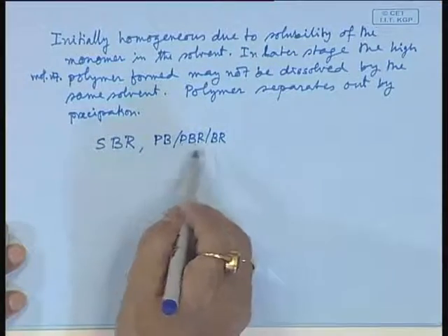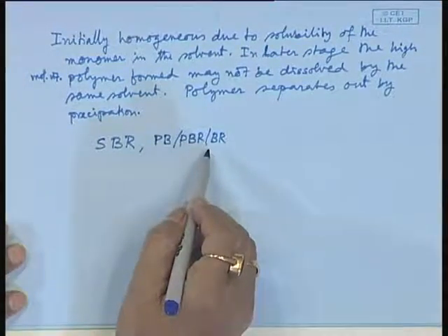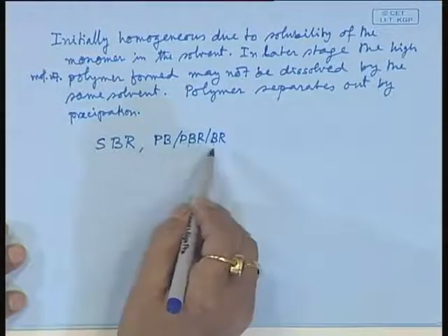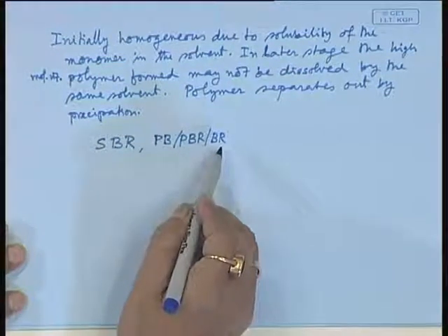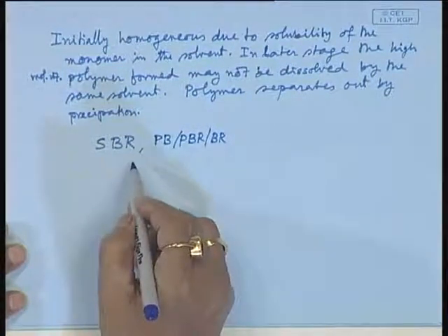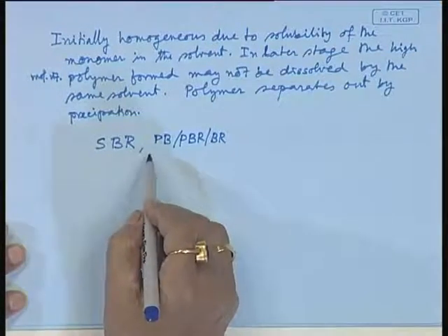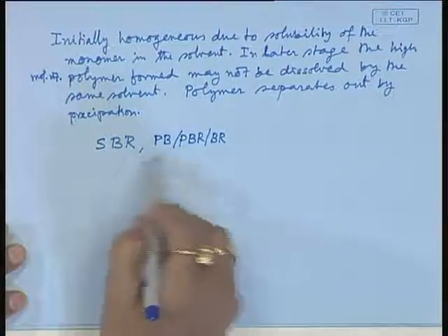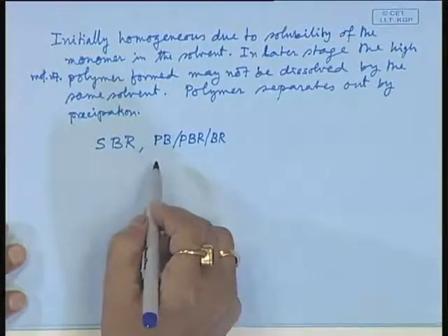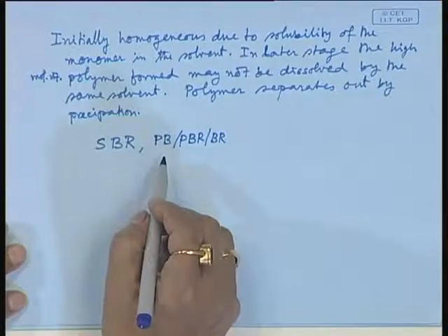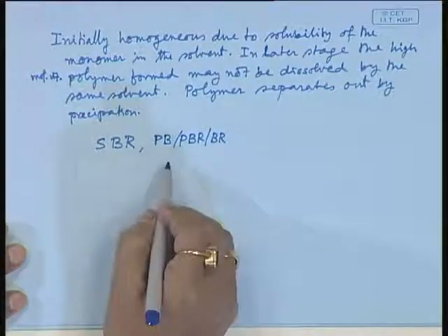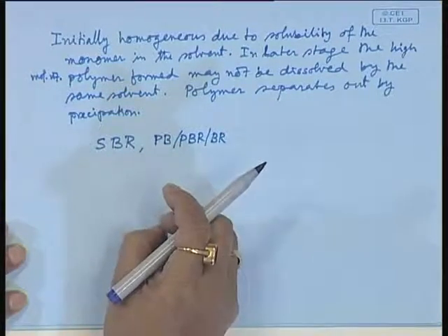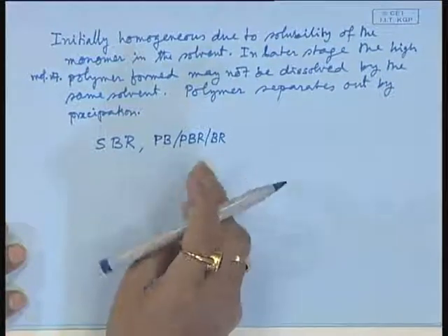The polymer is same, polybutadiene rubber. Now, this styrene butadiene, polybutadiene or other polymers are made by solution process or suspension process. Normally these polymers are not synthesized by bulk technique, they are polymerized by solution technique, solution SBR, solution BR, etc. Their grades are mentioned as solution SBR, solution BR, like this.